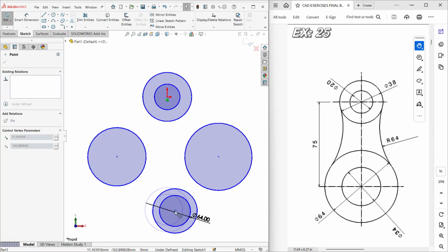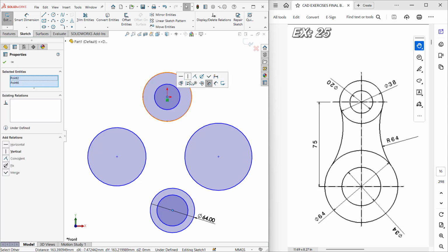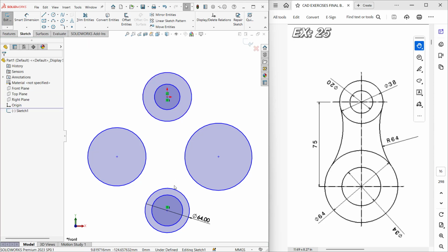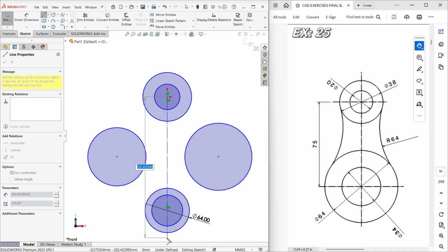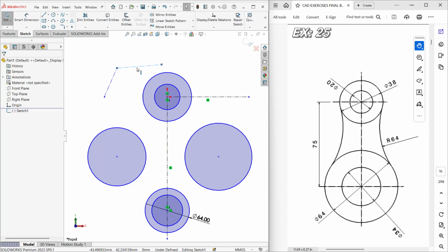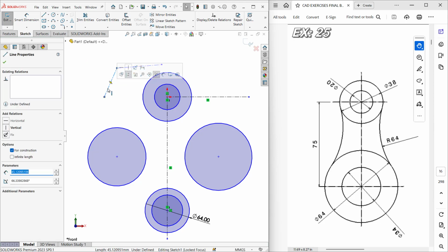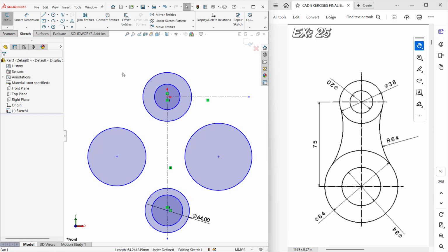Just select the control and define the geometrical constraints. First thing is I would like to maintain the relation vertical for this one. So just select these 2 points and select the make vertical option from the quick access tool. This is done. And now I need to have the reference construction lines. You can directly select the for construction instead of creating again. So I'll simply draw a line like this, and here also I'll simply draw one more line. Left click, hold, drag will create a single line, and if you simply left click and try creating like this, it will have the continuous line. Okay, remember that. So I'd like to remove this. Press the delete key on the keyboard so that you can remove that.